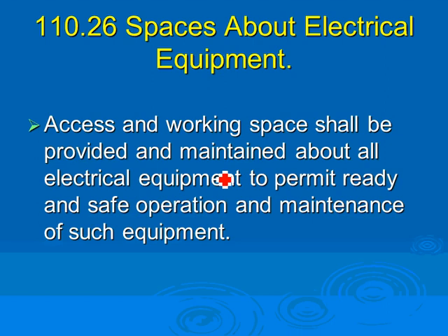Space about electrical equipment. The NEC code book, guys, as well as 70E, requires you to maintain clearances because of the shock hazard and the arc flash hazard.